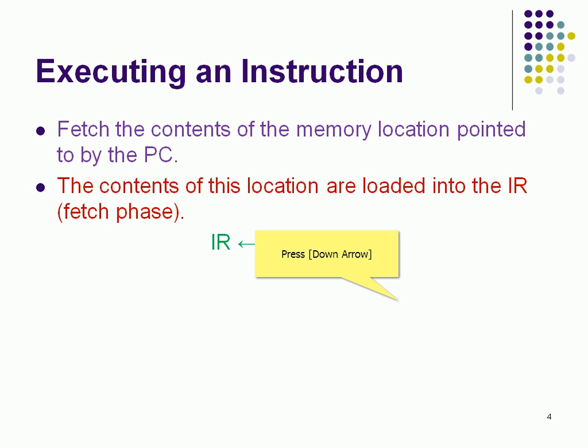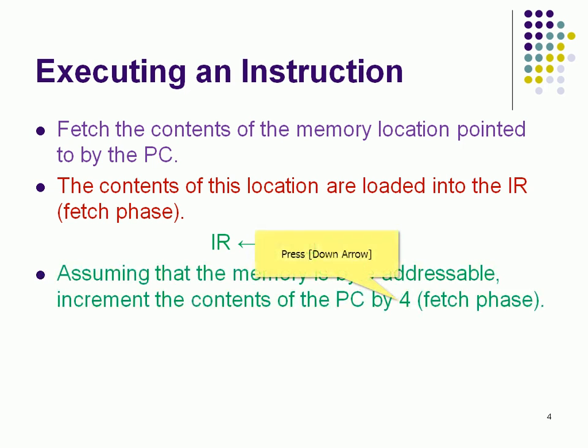So what is a PC? It is the current instruction address. So the contents at the memory location, the data or instruction, is going to be brought and travel across the bus to reach the CPU premises, and there somebody has to welcome it, that is, IR is going to be placed for that. So the instruction register is also responsible for the fetch phase.